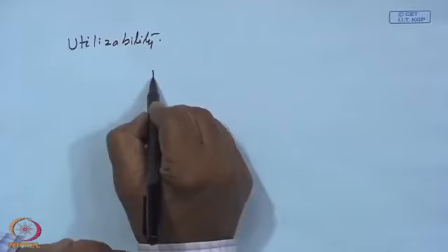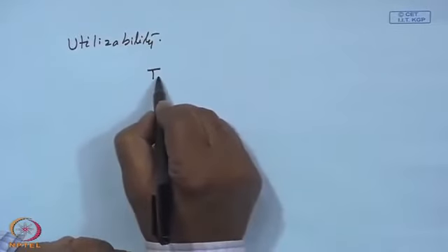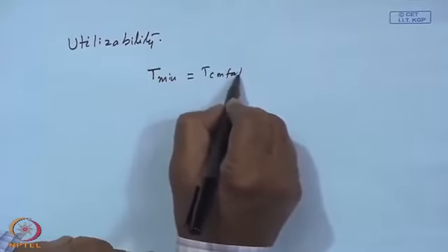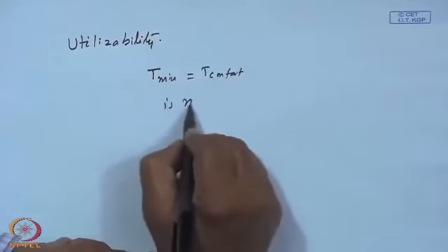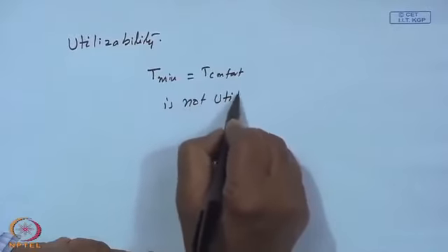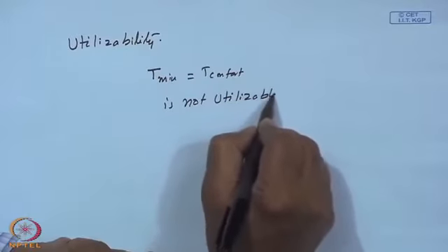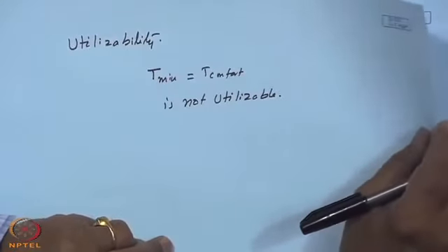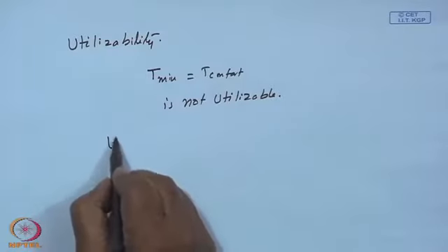But in the case of passive heating, the solar radiation above a certain level comparable to T minimum equal to T comfort is not utilizable. In other words, once the room is at T comfort level, any solar radiation above that level shall not be utilized, and hence the concept of unutilizability.